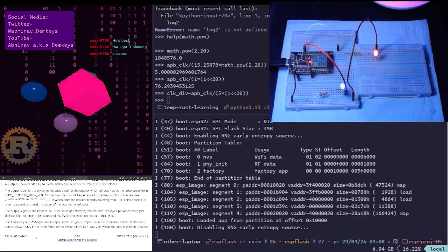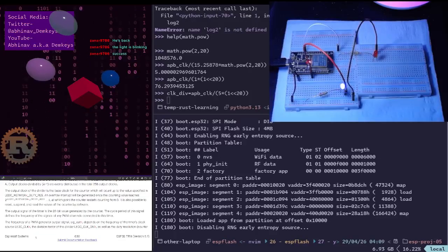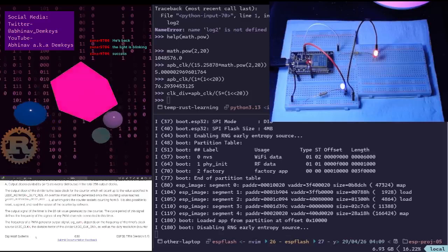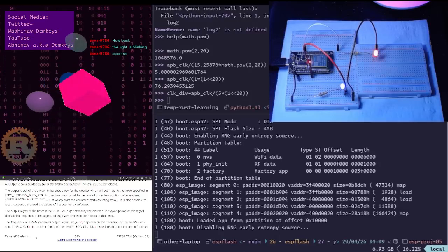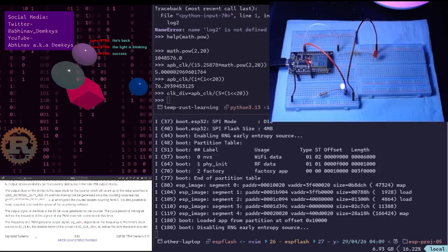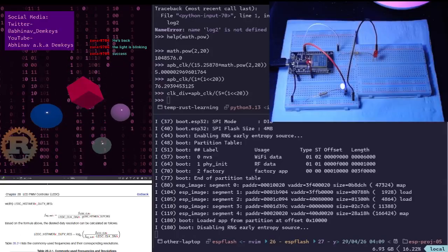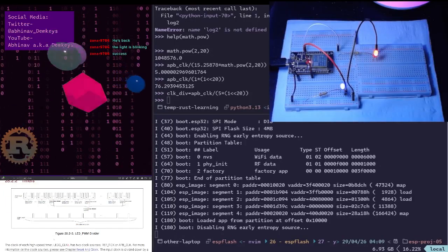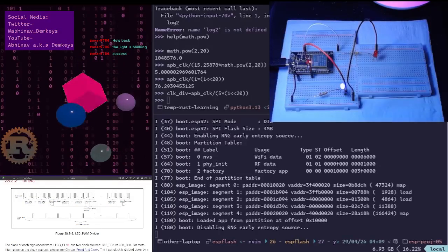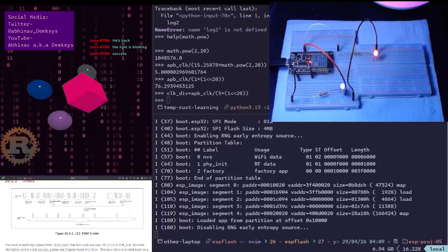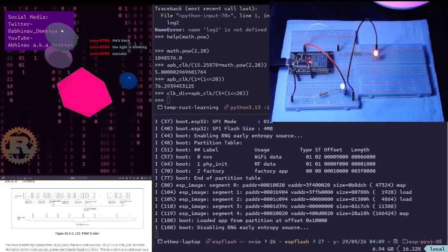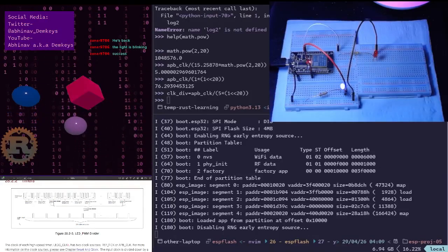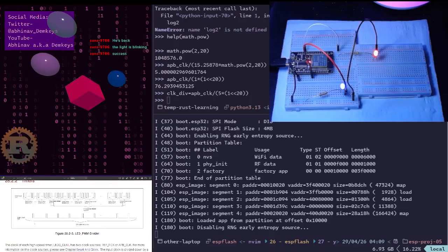But then the divider also determines, oh, the divider determines. See, this is where understanding the math becomes important. The divider is what determines what gets counted as one count in our counter. The divider is telling us that every n number of pulses, one pulse is considered one count.